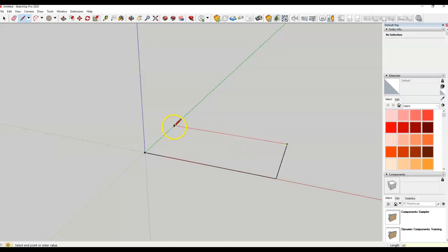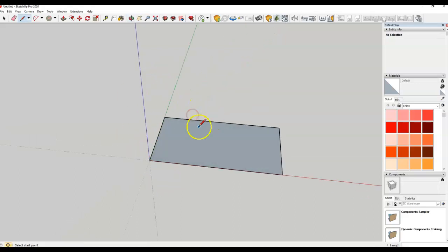And I'm just going to complete the rectangle. Again, along the red, I'm going to see the red line. So make sure I'm drawing it straight, because visually you're not going to know because of the perspective. So you have to use those dimensions and then draw along the green and close it off. And when I close it off, we see that we get the surface here.